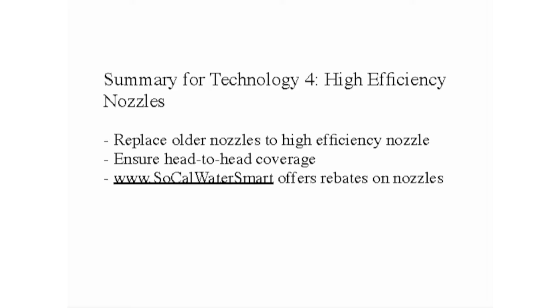So in summary, high efficiency nozzles: if you're going to take the time to replace the head, you might as well change out the nozzles. Use the same manufacturer, so you don't have different manufacturers on the same zone. Same manufacturer on that zone, and either fan spray or rotating. We want to make sure we have head-to-head coverage, from one head to the other. And there are rebates on these kinds of nozzles. It's normally about $2, some places maybe a little bit more. So it covers some of that cost.